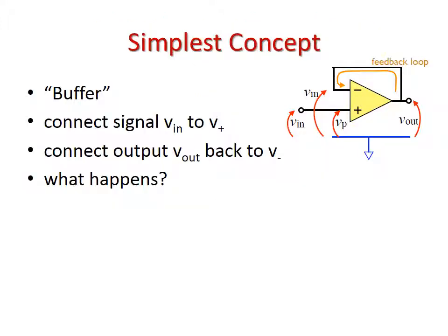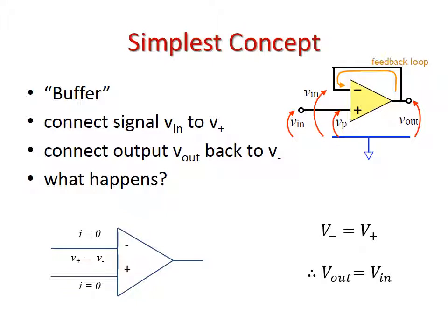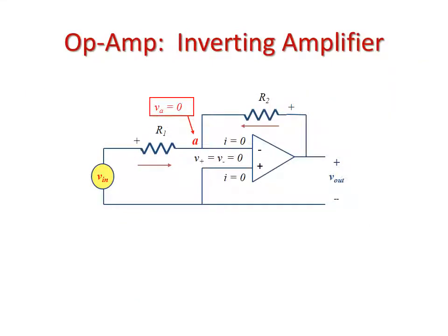Again, the simplest concept, and we've looked at this one multiple times in class, is a buffer circuit. A buffer circuit has a gain of 1. There is no gain, so it's essentially a unity gain. Whatever Vin equals is what comes out. So whatever signal comes in, the exact same signal comes out. Why is it useful? Because it helps protect circuits. Our Vin equals V out. However, since no current is going in or out of the negative terminal on that op amp, we've protected that circuit, giving it some buffer protection in case some accident happens later in the circuit.